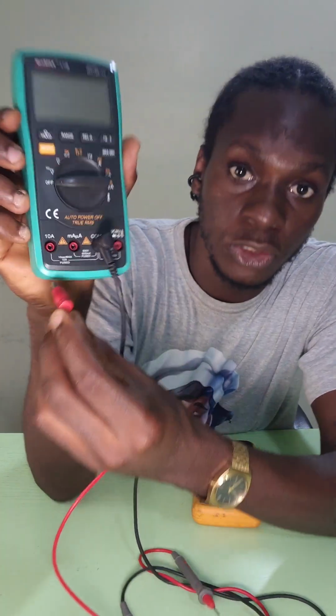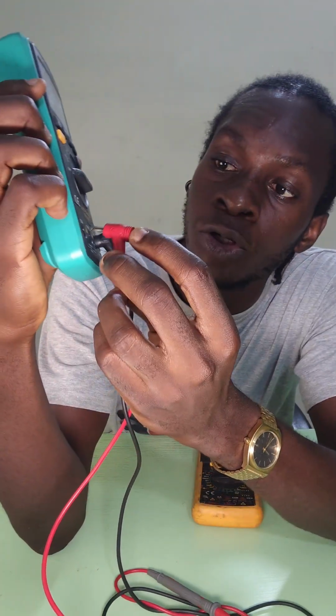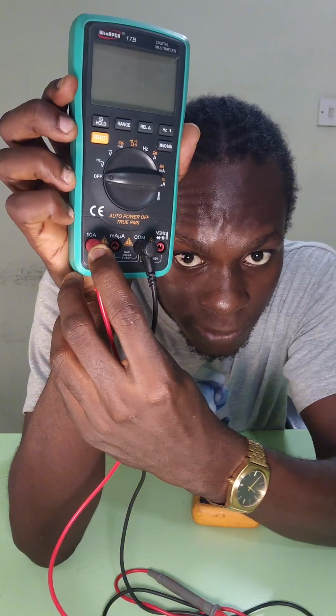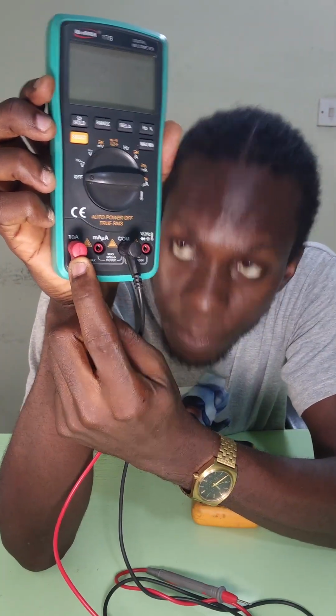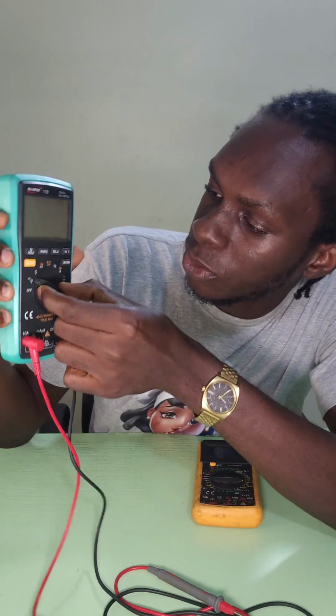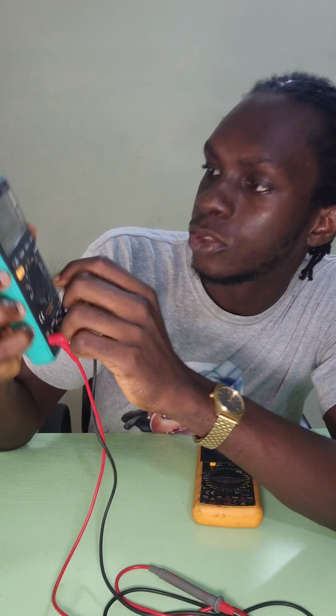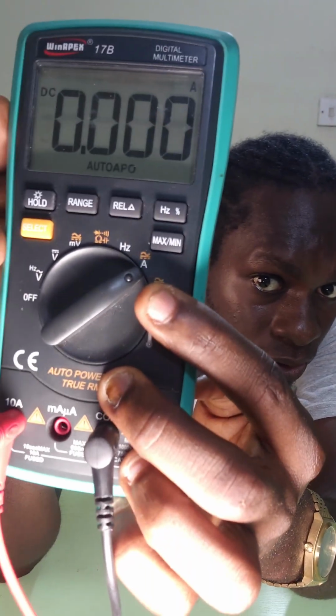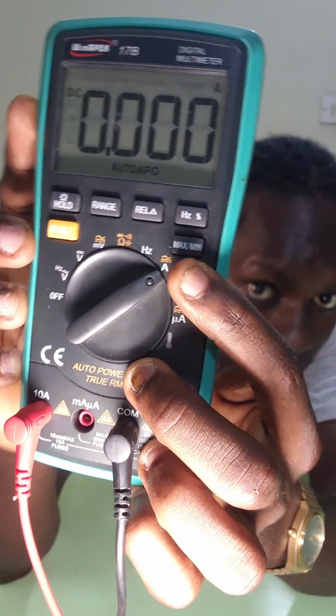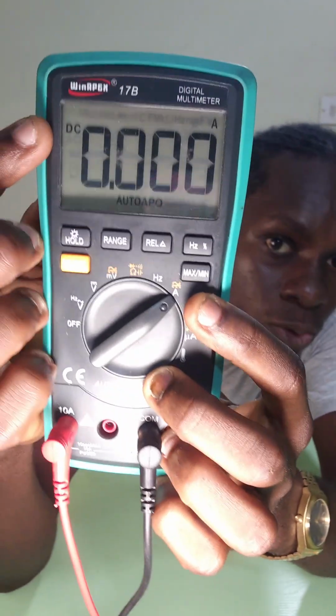So the current we want to read, we don't know exactly how big or small it is. So I'm going to be using the biggest one. This meter can only read from 10 amps below. So we'll have the red probe on the ammeter socket, and we'll now switch the meter to A. So on this auto range meter, you notice that the A is for both DC and AC. It has both symbols. So when you put it here, you look at the screen.